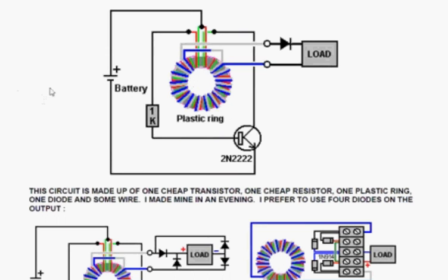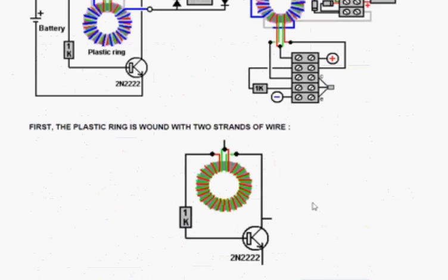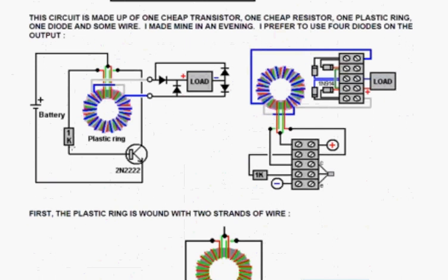And there are 2 windings on this. Both of the windings are bifilar. So initially you wind all the way around the toroid with 2 strands, and then you connect it the standard way for a Joule Thief. This is a typical Joule Thief arrangement. But then you wind a second layer round in a bifilar winding. This is the layer that's shown in gray and blue, if you're not colorblind. And about 30% of men are colorblind.